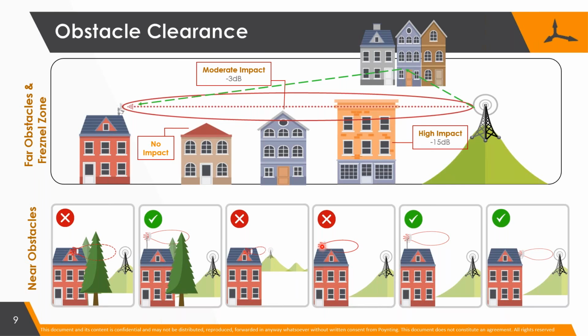Once again, you can move it there just to make sure that you've got a clean beam facing the base station. And of course, that part is still cut off there, and it's much better to get it so that within the beam of the antenna, and we always publish the beam width, you've got no part of the house or the building obstructing the signal. Best is, of course, always, if you haven't got obstacles, you can just go on that side of the house that faces the base station.